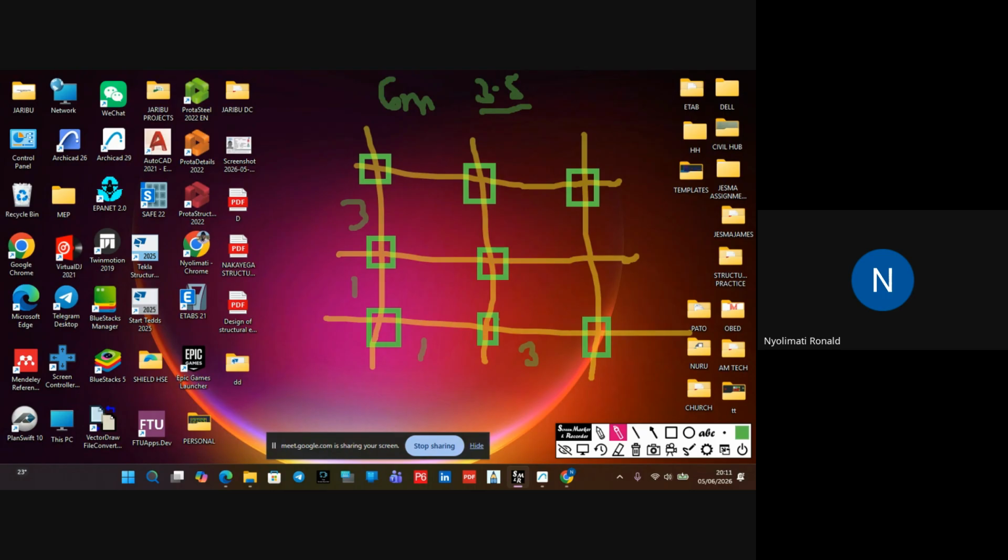No, it's the beam which carries in a trapezoidal format, but of course the column carries the weight of the slab that it carries plus the beam, in form of the surrounding area, like halfway of it.